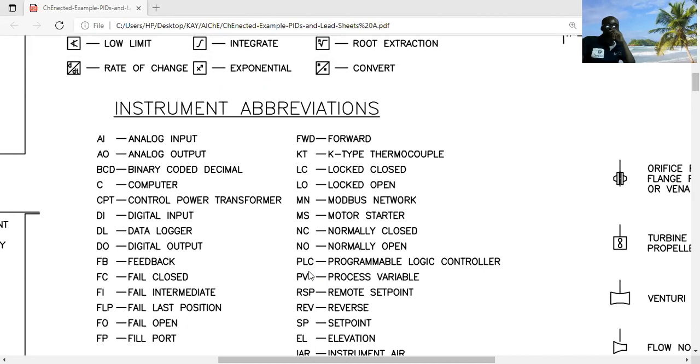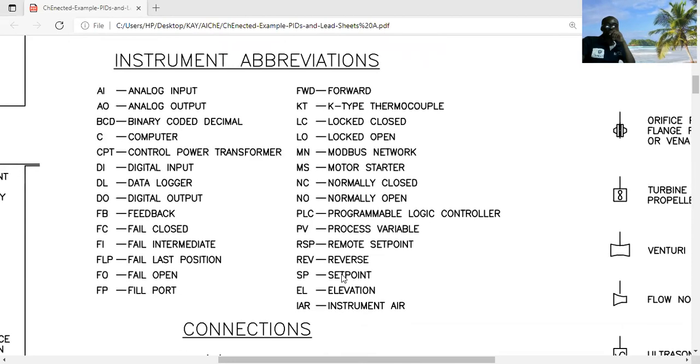the process variables that are there within your flow lines. We have the set points, and we have elevation. The set point is mostly on your PSV and PRV, which you set a set point for. If those pressure safety valves see pressure above what you designed them for, then they have to open. That is a command. So you put them at the set point pressure.